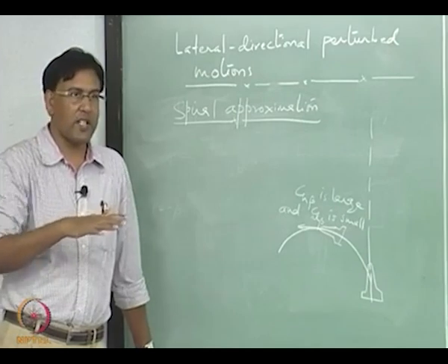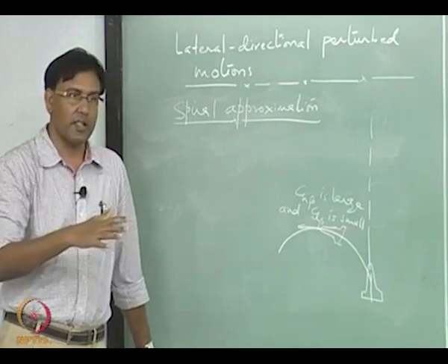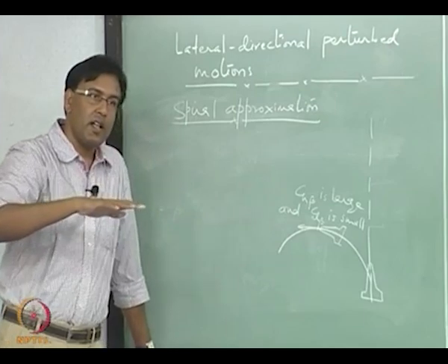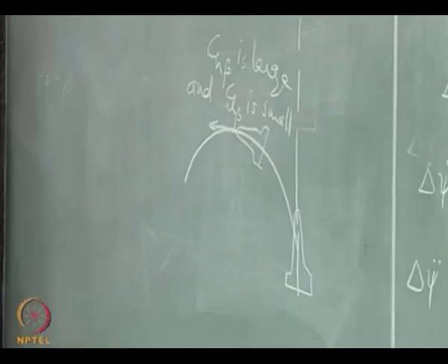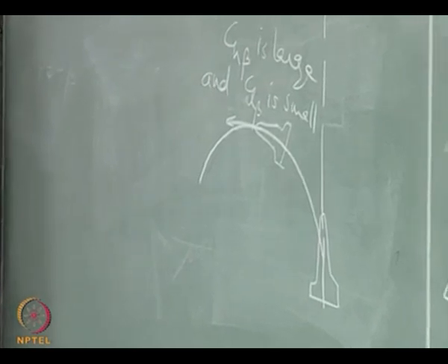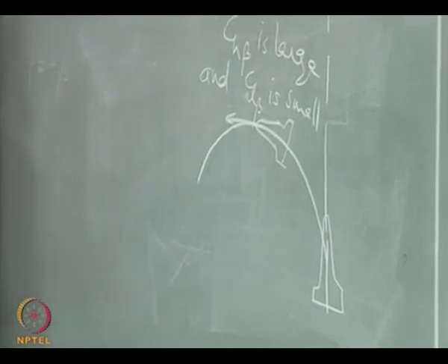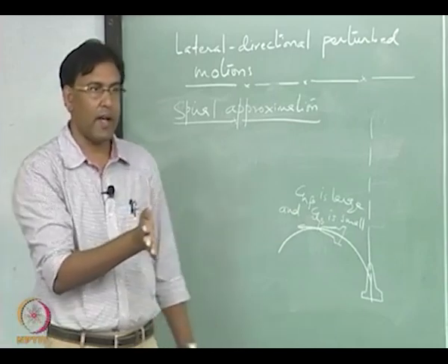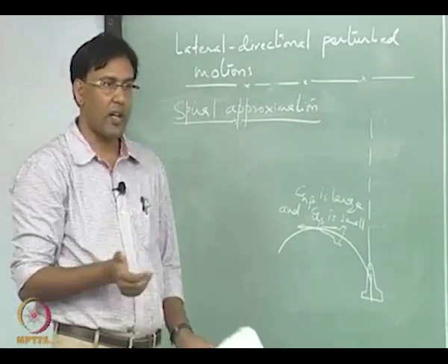So, it is following the velocity vector, starts doing this, and as it progresses on this curved path, because of increased bank angle, this turn becomes tighter and tighter, okay. So, it is doing this, and also it will start falling down.